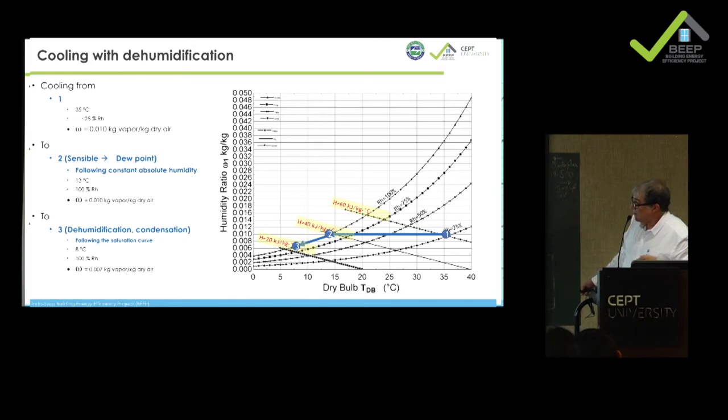And so this is typically what happens in a cooling coil in an air handling unit, where you have water at maybe 6 degrees, where you are cooling first sensibly only, and then when dehumidifying, you are removing a lot of latent heat. So you can see that these energy lines, we are crossing them in a sense. It goes from this one, and we are going down almost to this one. And then we will come in more detail to how it relates between dry air and latent cooling.